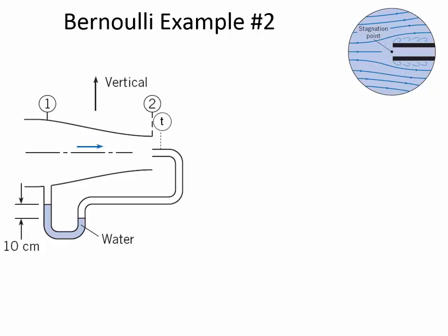So just outside of the tube, the air still has velocity. So think of it, there's some energy trapped in that velocity. But then when that streamline dead ends at the opening of the tube, all of that energy that was velocity is suddenly exchanged into a little more pressure, an increase in pressure.